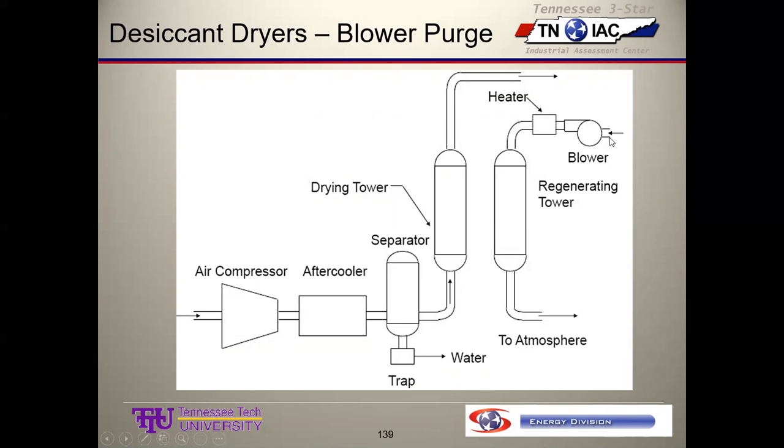Go over there, look around on the back side of it. If you see a blower sitting there, you go, oh, this is a blower purge unit. If there's no blower, then it's not blower purge. And you look and see if it's got some sort of a heating element. If it's got a heating element, no blower, then it's heated. And if it doesn't have much at all besides the twin tanks and some piping and some valves, then it's heatless, and then you're in the 15% vent rate. So they're really not too hard to identify once you've seen a couple of them.